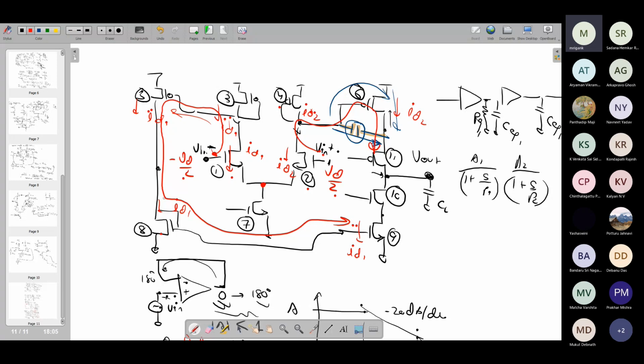Of course, what we see is that the current magnitudes are the same, even though it is gm6 in this case and gm9 in the other. So we can find the overall transfer function in terms of all these gm and ro, and then we can see that ultimately the magnitude of the gain will be the same. Can you do that? I call this path 1 and this path 2. So let us quickly write it over here. Path 1, what is the gain overall?